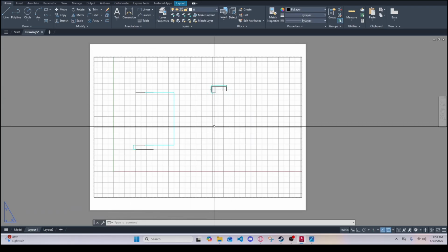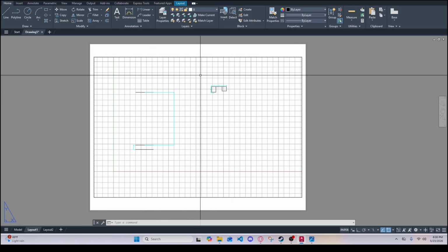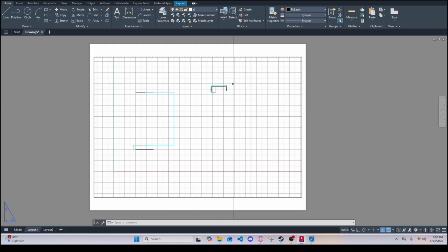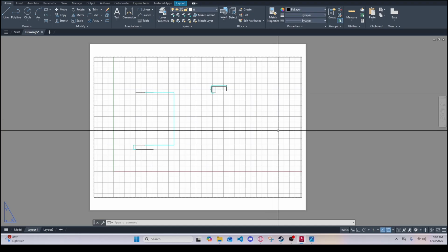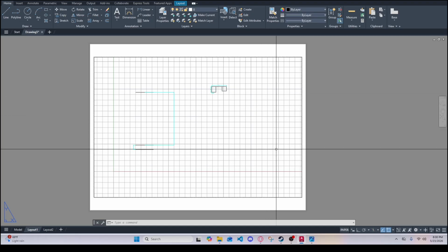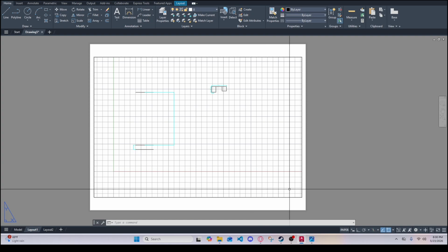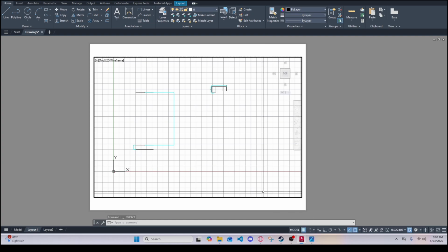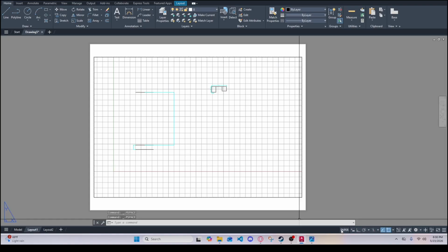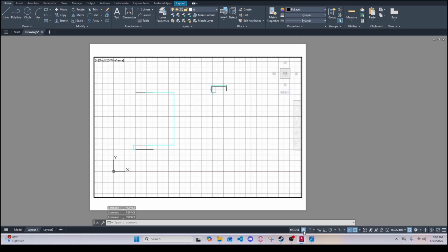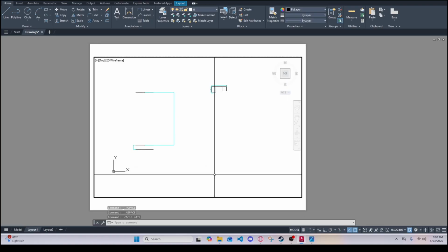And now you're also probably wondering, well, how come the grid lines aren't showing up when printed? Well, you don't want it to show up regardless. But something you do want to get rid of is the grid lines, just because it makes it easier, at least for me, to view it. If you go to model space by just clicking this again, you're going to see these dash lines. This can be your grid mode. If you click it, it removes it. So now you only see what's actually clear there.